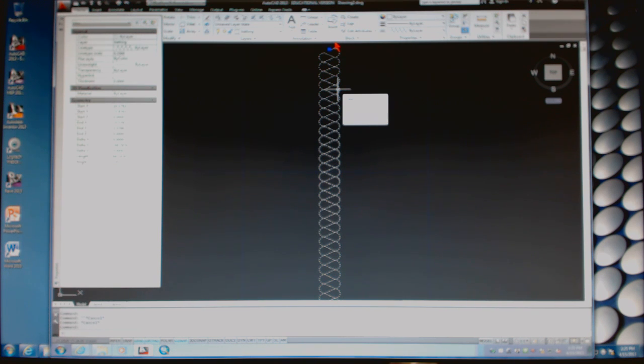So you should end up with, I think, five separate sheets of paper. The only thing is now, every bit of this has to be drawn inside one file. Draw all this in model, and then you have 5 different tabs for paper space. Now, this is going to be drawn on an 11 by 17 sheet of paper. So I'm throwing a monkey wrench into everything you've learned.